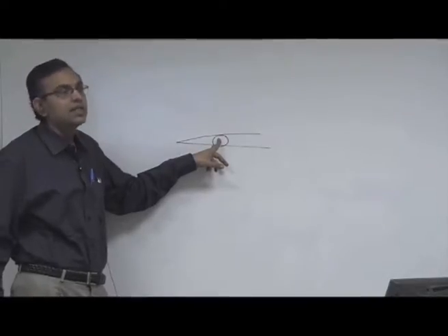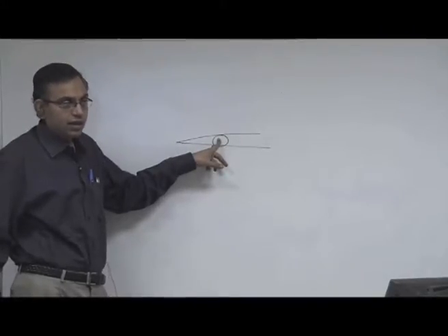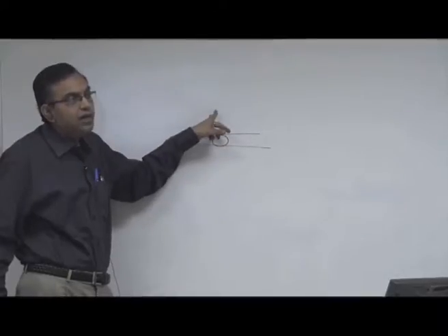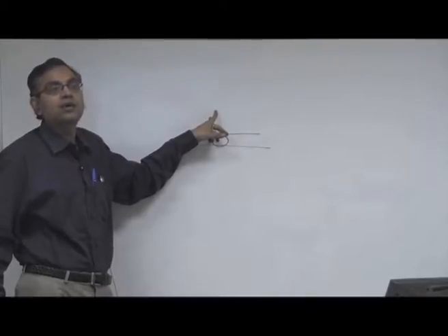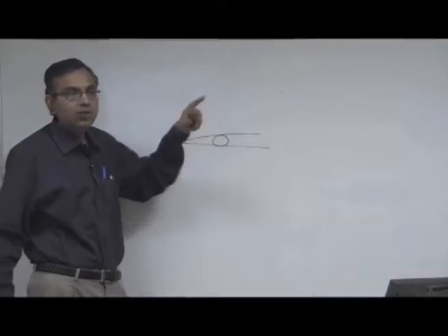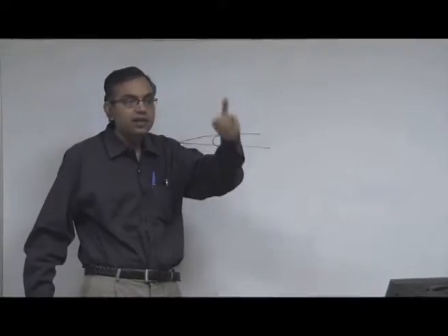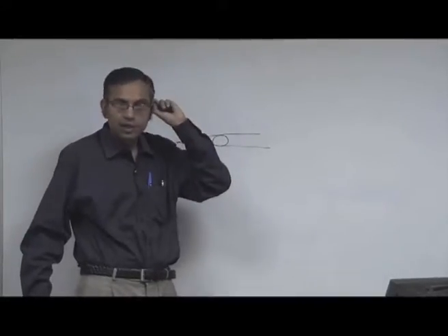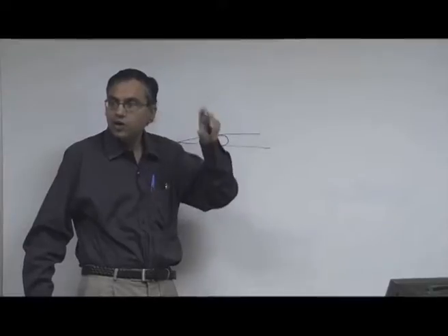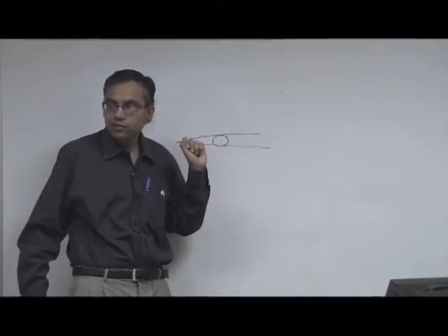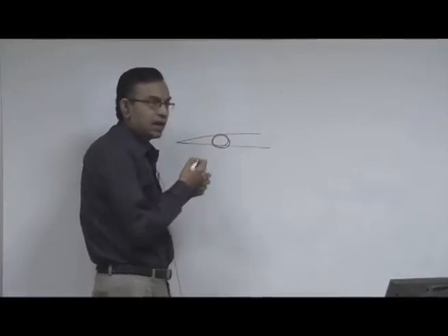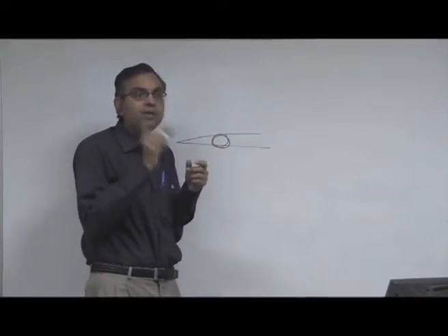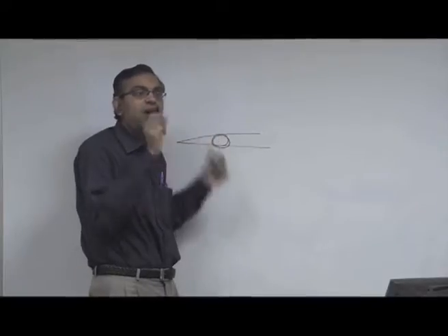If we neglect this region altogether, the problem is that we neglect the viscous effects altogether and mathematically we bring down a second order PDE to a first order PDE, because when viscous effects are not considered, the Navier-Stokes becomes a first order PDE, second order effect is not there.